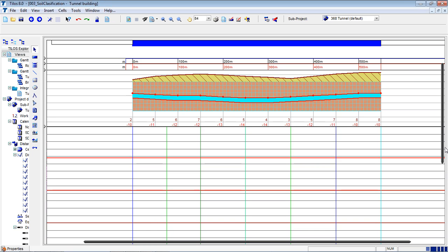And I go to my boss and say, listen, we need to make soil classification analysis in this area, or buy some ready soil classification analysis, or ask the owner to provide us soil classification analysis, to be able to estimate the real TBM work. And if my boss hears that it will have some cost for our company during the tender phase, he will maybe not be happy. He can say, listen, just decide on some average. And I call my friend, and my friend will tell me, well, Tekin, it depends again. It can be like 10 meters per day, 30 meters per day.